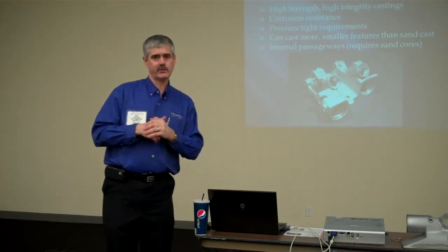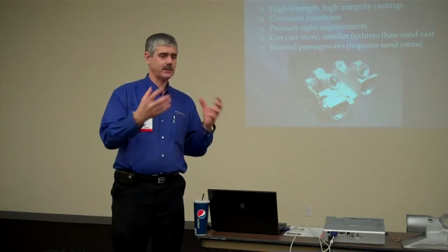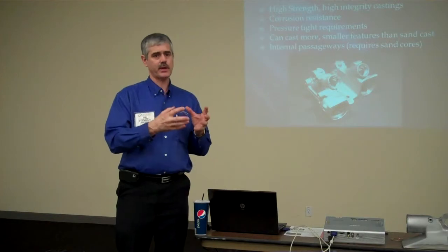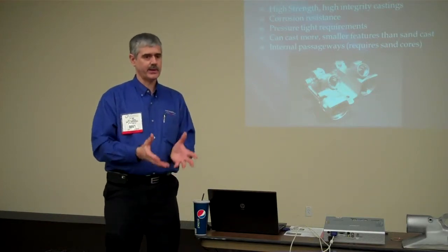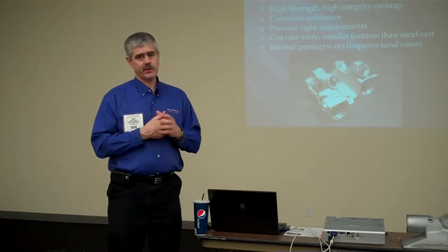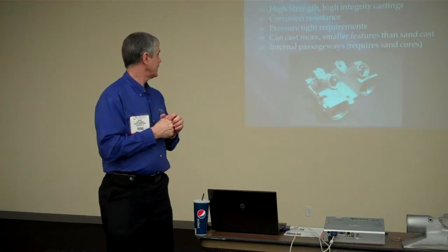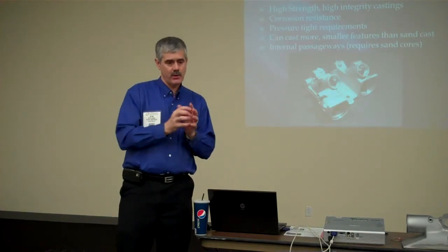With die casting, because we inject under pressure, the air in the cavity doesn't have enough time to exit, and it gets entrained. You get entrained air inside the aluminum. With permanent mold, we'll fill the mold slowly and tranquilly and get the air out of the cavity ahead of the aluminum, which means we get uniform properties throughout the whole part. And they respond very well to heat treat.